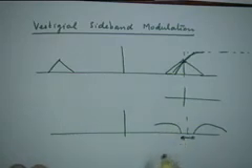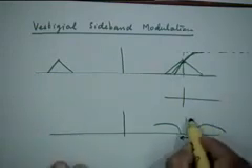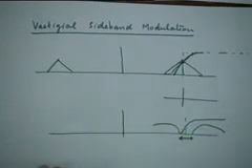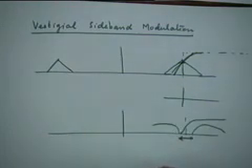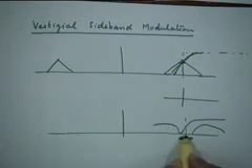There is a band here in which there is no signal energy, and that gives me flexibility in designing this filter. The filter design can be done. I don't need a really sharp cutoff filter, in the sense of a brick wall characteristic. There is a band available over which I can gradually roll off the characteristics of the sideband filter, which is not going to be available to me if this band was not available. You appreciate this point? So in certain kinds of signals, and also this is a second point.